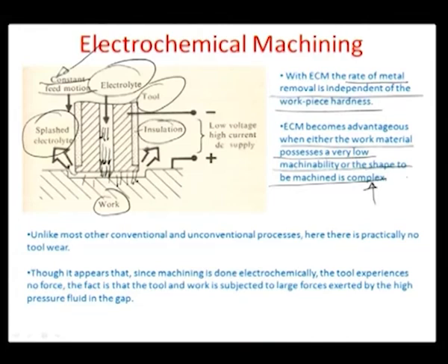And unlike most other conventional and unconventional processes, here there is practically no tool wear. Okay, although that's not true really, because sometimes great pressures get generated in this small gap here, which may be a reason for tool deformation, even if not wear. But the idea is that because there is no deposition on the tool as such, or any change in the characteristic of the tool, whatever comes out of the workpiece goes into the solution and gets precipitated, and this precipitate is getting carried away. So the tool should be left alone by and large by this process.